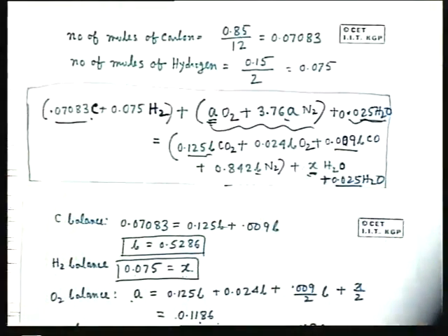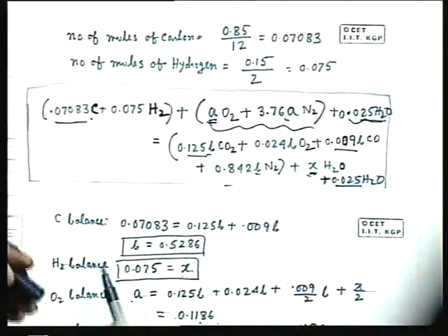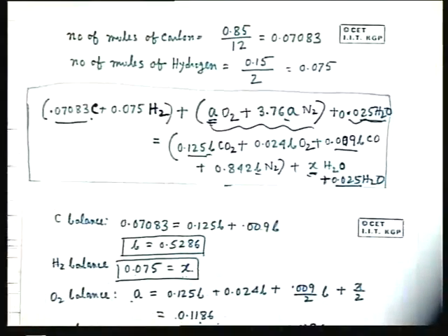So this gives you a clear idea about the mass conservation. You write the chemical equation in terms of the moles, and try to find out from that what are the known and what are the unknowns. You have to assume some number of moles as the unknown, which will automatically come out if you make the conservation of mass of a particular element taking part in the reactions. Then the mass balance will give you the number of moles. This is as simple as this. Okay. Now I will come to the conservation of energy or first law analysis.